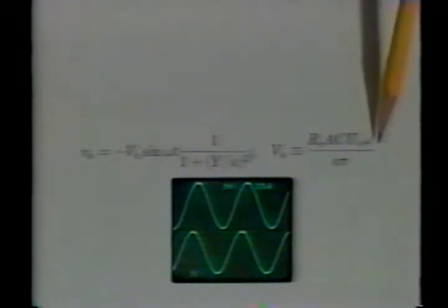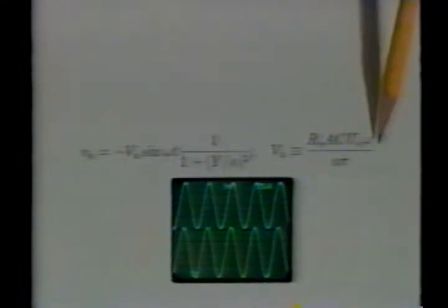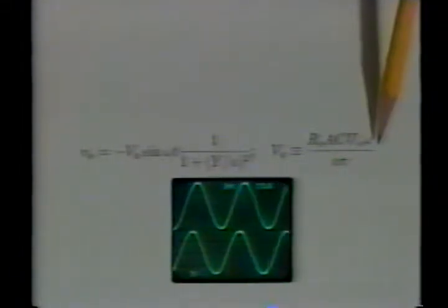Also, charges of opposite polarity are induced on the other side of the probe, between the probe and the ground plane underneath. The result is an output signal that no longer increases with frequency. A frequency response of the probe voltage that does not increase linearly with frequency is therefore telltale evidence that the resistance is too large or the frequency too high.